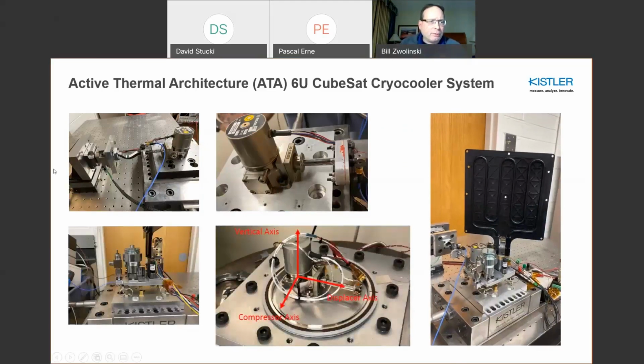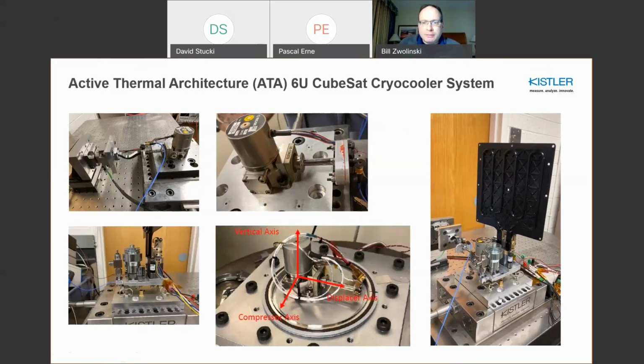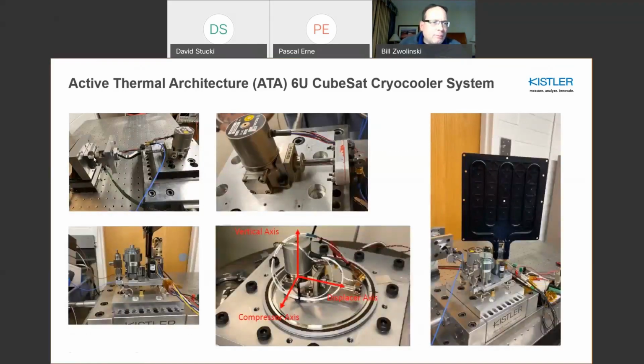What I wanted to show here was a couple of simple examples, while you see the video. Basically, this is a 3-component load cell, 9347, attached to the detector, or at least the thermal strap, right here. And this is the cold tip, and there's an accelerometer on top, 8763. Beneath everything is a dynamometer that's being used to measure the exported force and torque of the entire assembly. You can see here a particle damper on the cold tip.